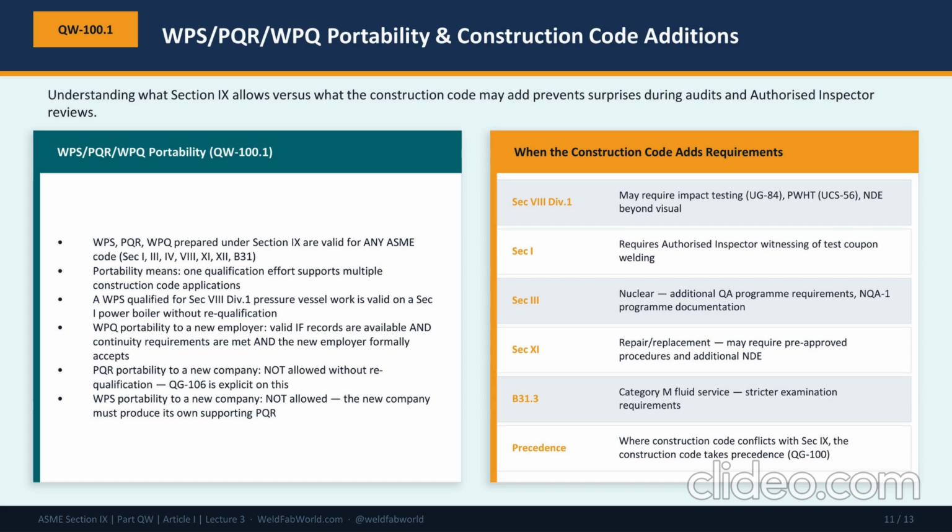WPS portability to a new company: same restriction. A WPS references the PQR of the company that qualified it. A new company cannot pick up that WPS and use it in production without their own supporting PQR.